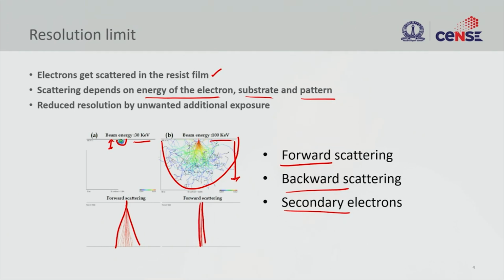From this we should not come to a conclusion that high energy beams are much sharper and then we can define very fine features. The real reason here is that the exposure of the electron beam resist does not only depend on forward scattering, but primarily depends on the back scattering and the secondary scattering. All these scatterings that we see here are secondary scattering, and then the back scattering that you have. So once you achieve the necessary threshold, the contrast curve, you remember.